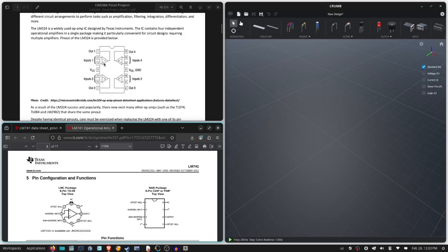And once the plus or the supplied voltage is greater than the reference voltage, the output will turn on. Now, we have 4 op amps, which is precisely what we need. We have 4 outputs, 8 inputs, and we have VCC and then VEE, or in our case, ground. So it's 9 volts to ground, that's how we're powering this chip.